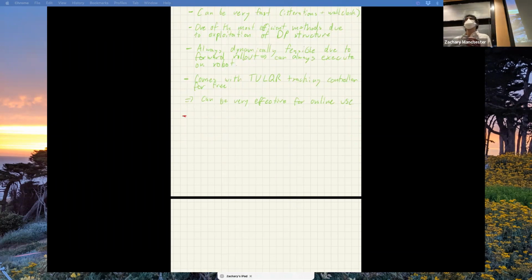Yeah. So how's the tracking controller? I remember for LQR, it was a stationary point. So there's two versions. There's the time invariant, which is a set point, and then there's time varying LQR, which is for tracking a trajectory. And so the K matrices that you get out of DDP or LQR at convergence are the exact same K matrices you would get from a TV LQR tracking controller.